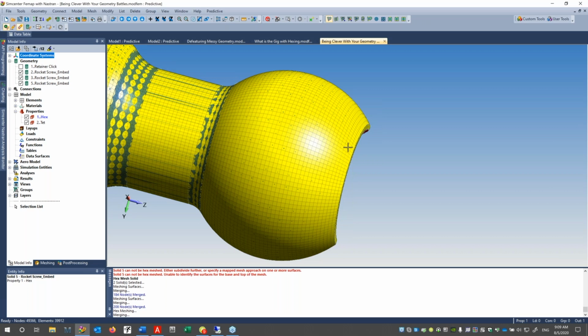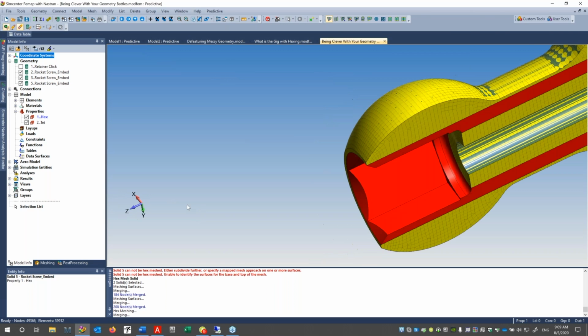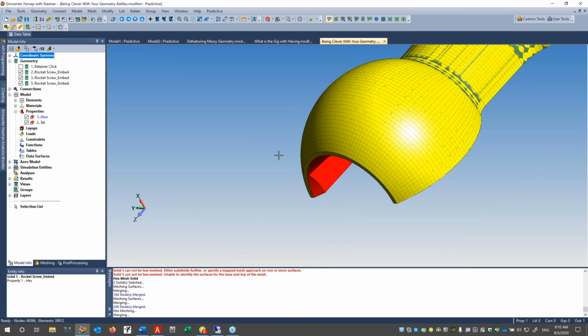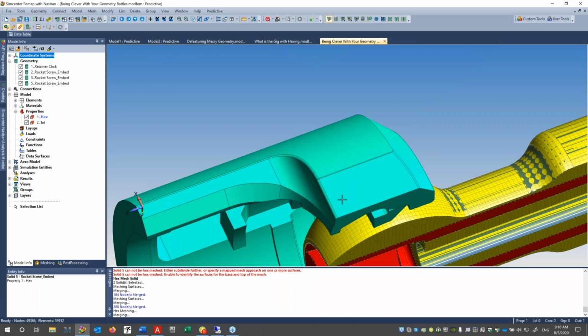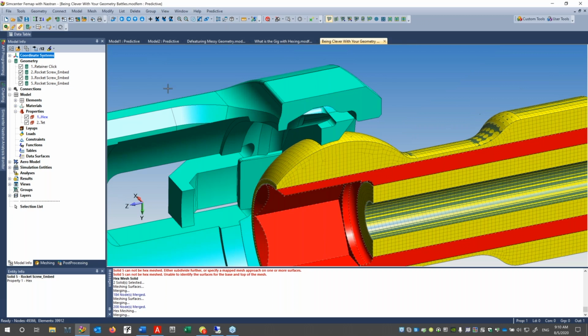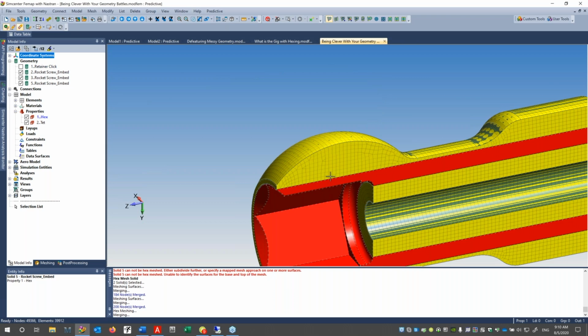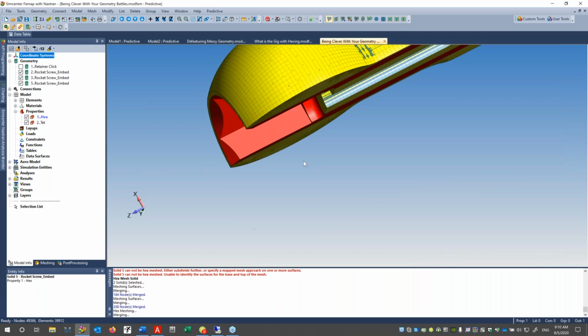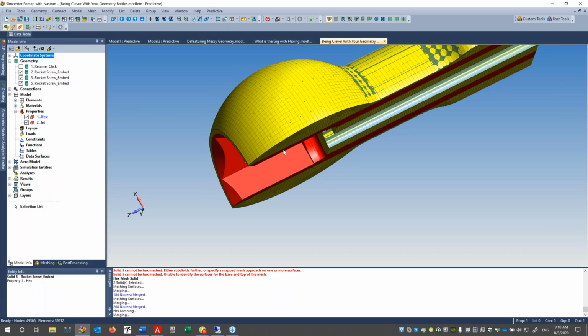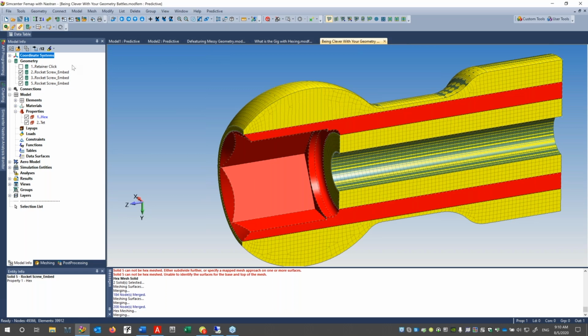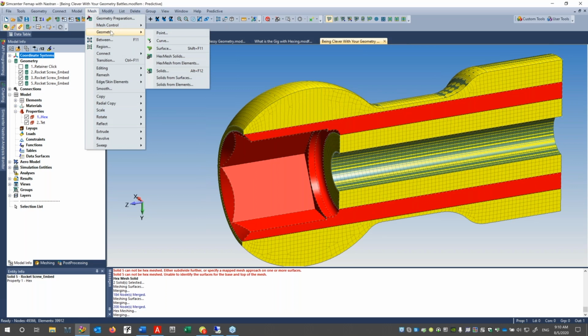And the reason why you want to hex on this is contact. And this is nasty, nasty, nonlinear contact. And there's nothing like a regular repeating pattern mesh surface to give you good contact behavior. As versus, I mean, you can get there with tets, but you got to be careful. It's a bit of a battle. But hexes, it's quite glorious.